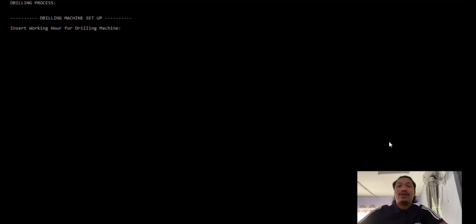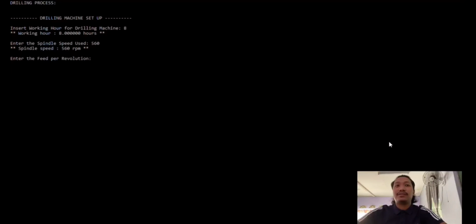Okay, now we reach the simulation of the program for the problem that we use in the drill machine. Firstly, we need to insert the working hour for the drill machine. In Mega Metal Company, the working hour is 8 hours per day, and we enter the spindle speed that we use at the machine, which is 560. Okay, enter the feed per revolution.